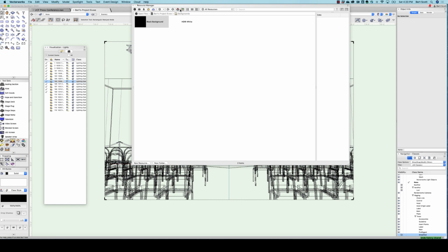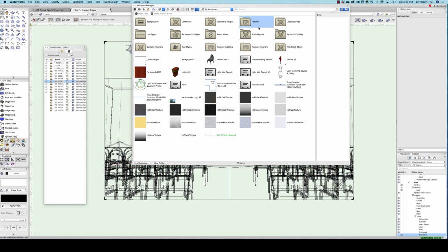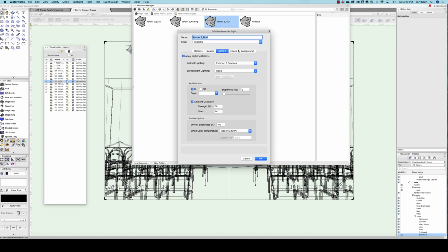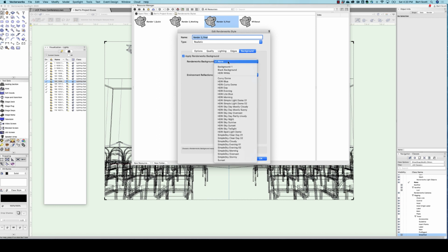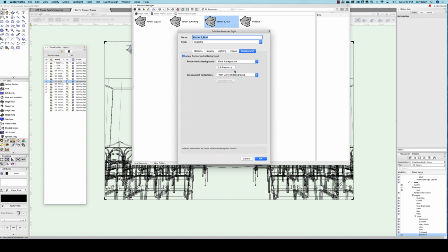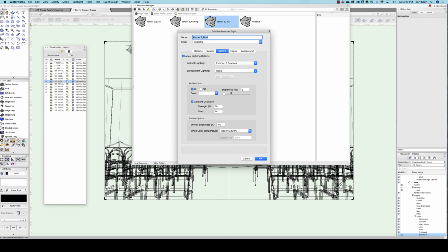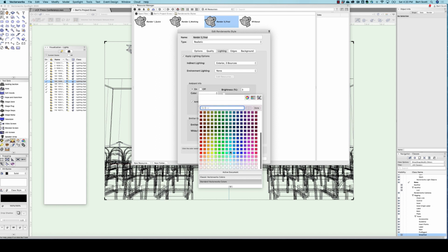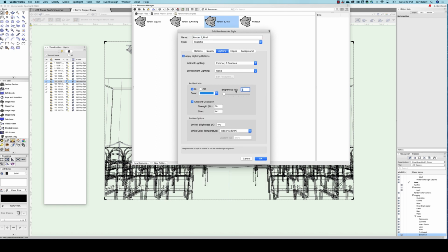So after you've done that, then you need to go to RenderWorks Styles. Right-click that. We're going to use the final render, but we're going to edit it. So edit. And we're going to make 2 changes. The background, we want to change the background now to the black background, which we just edited, that has the fog on. That's number 1. And then lighting, we're going to change the color of the ambient light to more of a light blue, somewhere along in there, and we're going to pump it up to 30.